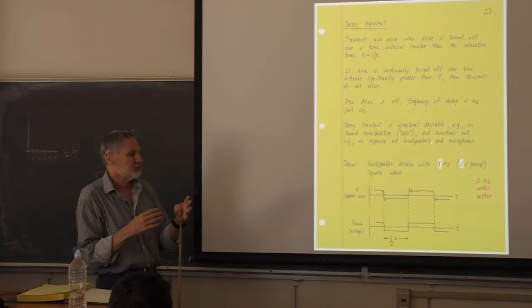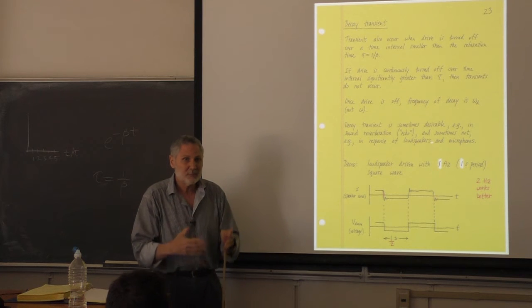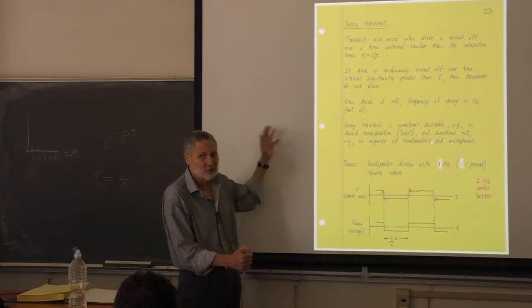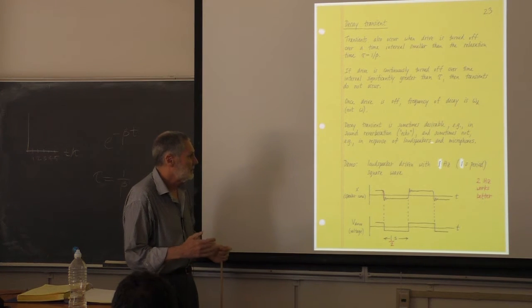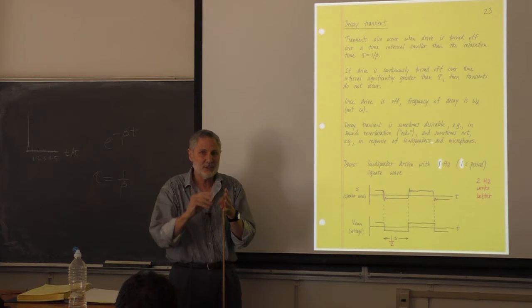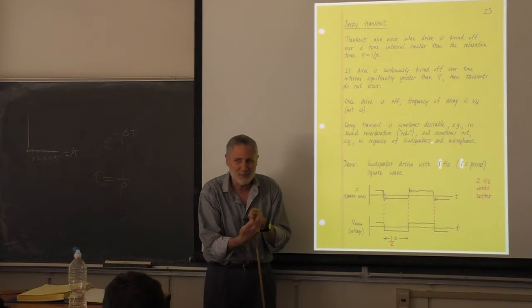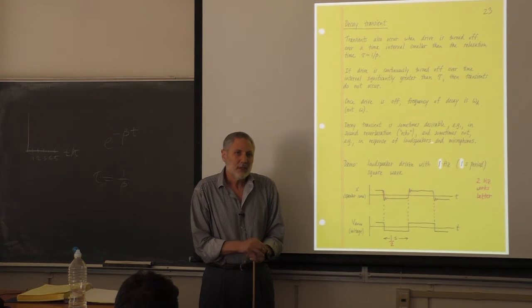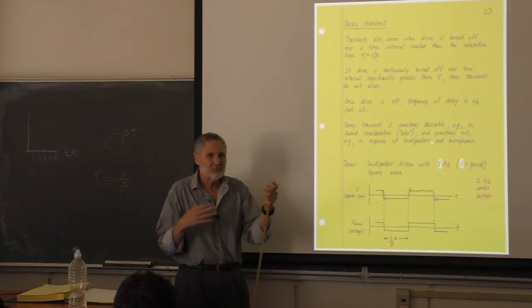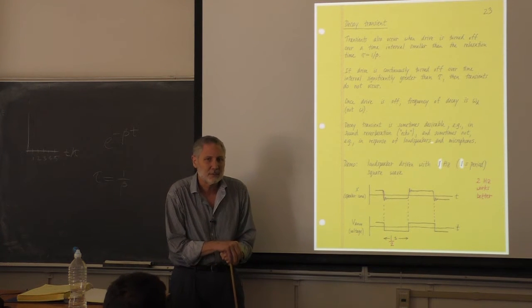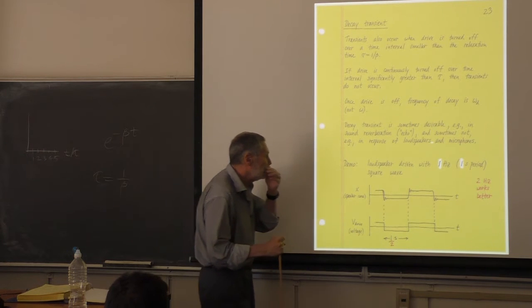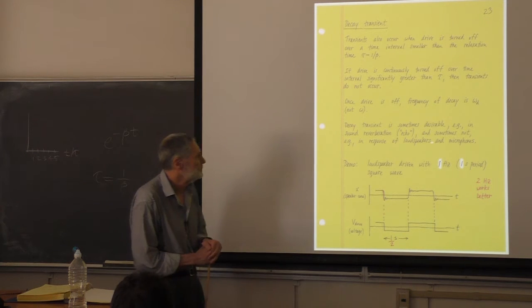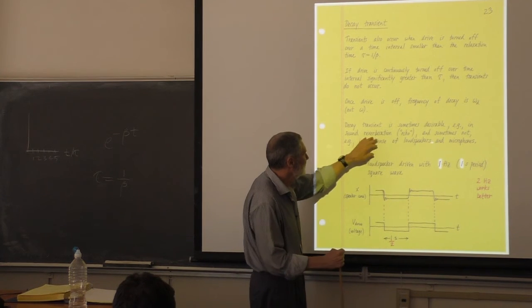Now, an electrical signal involves changes in drive amplitude, and it could be a multitude of frequencies, right? It can be much more complicated than what we've been dealing with. But the idea is there. When the amplitude changes, if you get a transient, what is that going to mean for the sound out there? You aren't getting faithful reproduction. What'll tend to happen is it'll get kind of muddled, and it won't sound right. So there are plenty of cases where you don't want these transients. People go to effort to reduce them, but they're not perfect, as we'll see in the demonstration shortly.